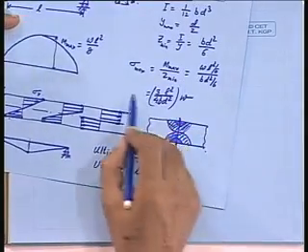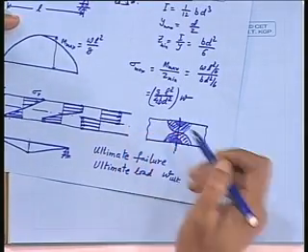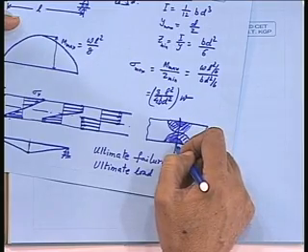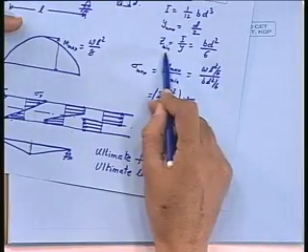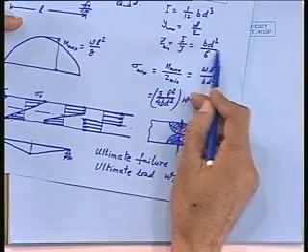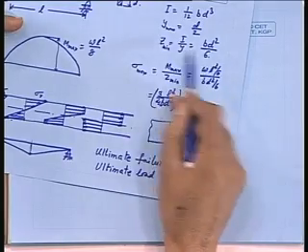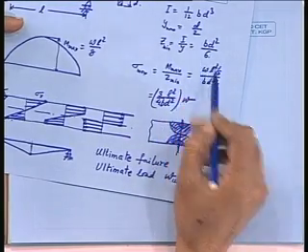And what is elastic moment? Maximum when the first fiber becomes yield point and the entire section is fully elastic. So from here you can get, isn't it, I by y, stress is equal to M by Z, or M elastic is equal to Z into sigma y. So that Z is elastic Z here.